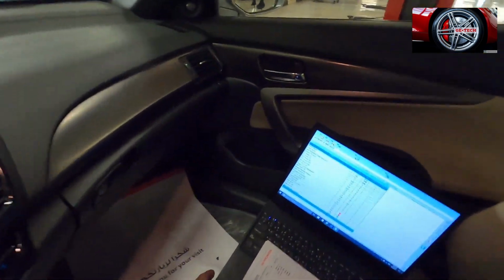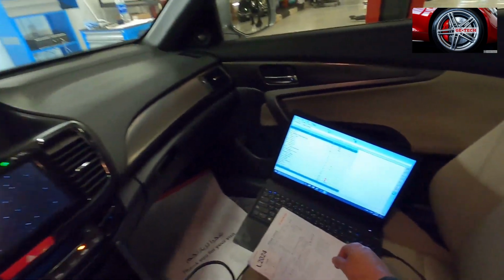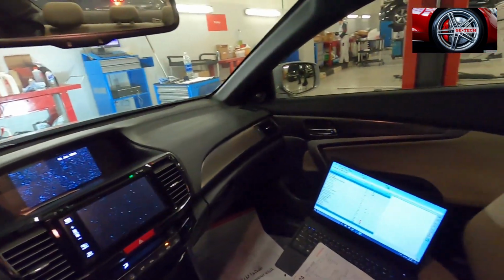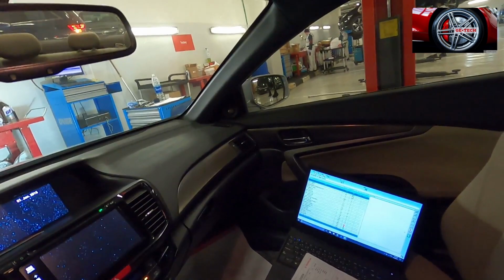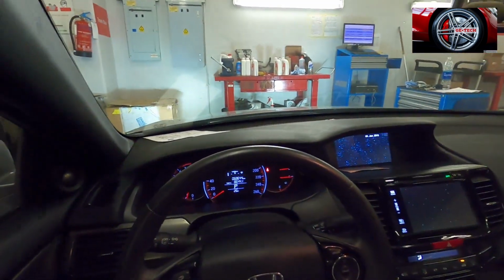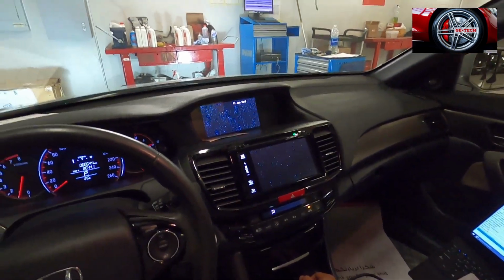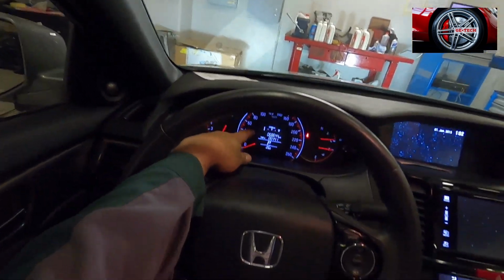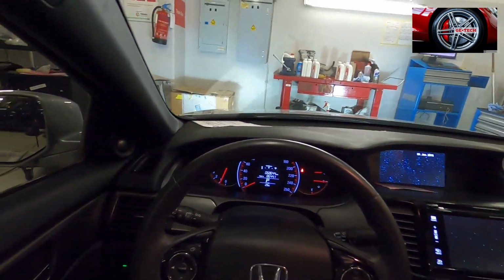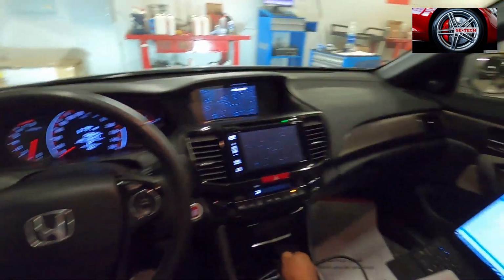We still have the HDS with us to monitor the data of the transmission, engine speed, vehicle speed, and the different sensors. So let's go now and perform the final road test. If the same DTC and MIL appear, it means our diagnosis is wrong.